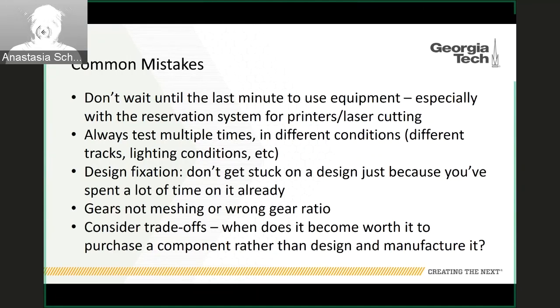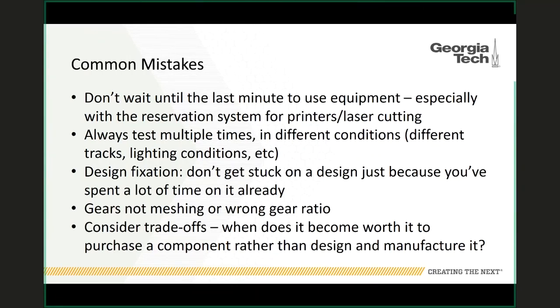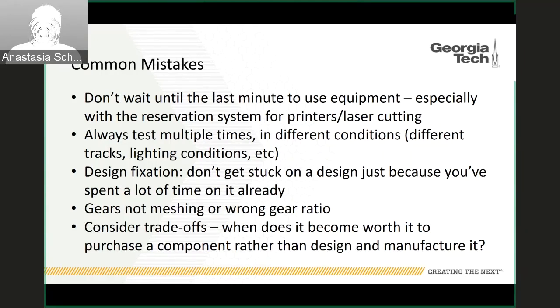Another mistake that is easily avoidable is gears that don't mesh or a wrong gear ratio. We'll see people 3D print gears, it takes 8 hours, and then those gears don't mesh. And then they get very, very discouraged from trying to fix it because it took so long. With some of the resources I've given you, like the gear generator websites or the SolidWorks Gear Toolbox, you should be able to avoid all those problems up front.